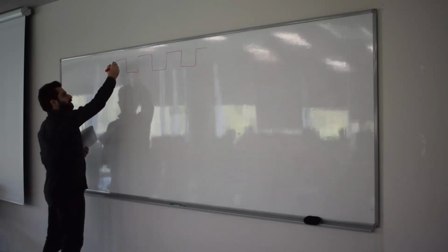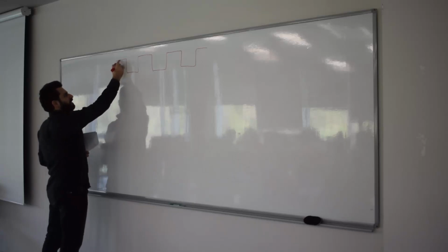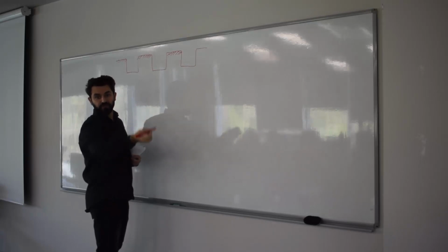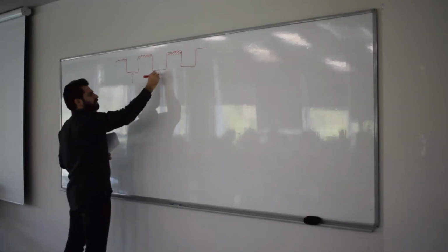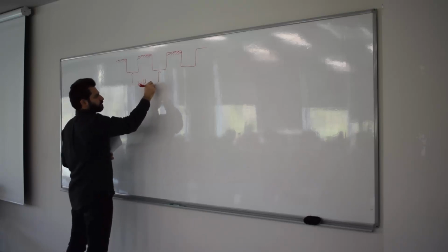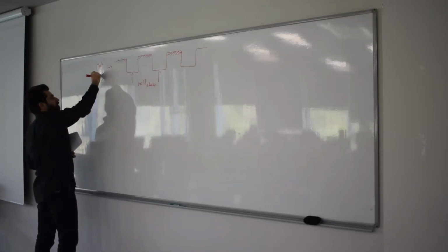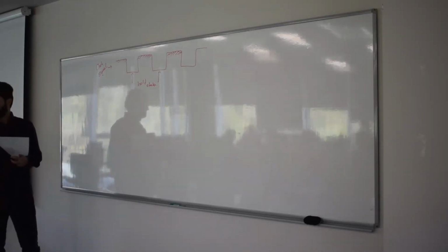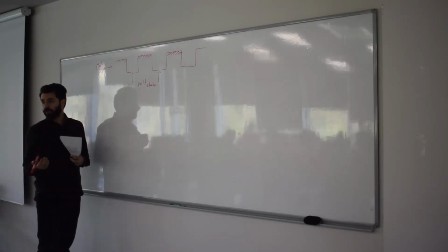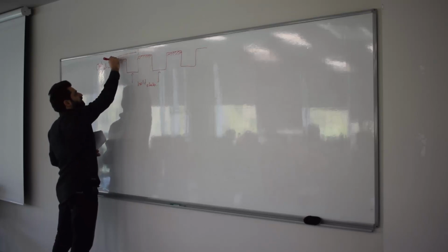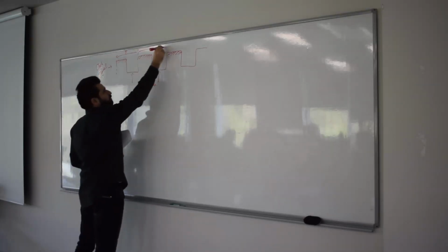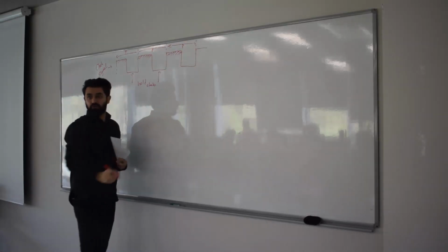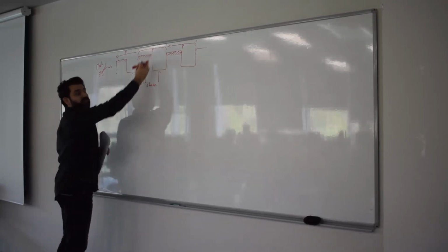So if you use a latch, these are the places where you're going to have a change, a copy operation of the input D. How about these? These are hold states. This is my clock signal. Now I'm transitioning to synchronous circuits where the clock is essential. Clock is a periodic square waveform, by the way. The period here is fixed. This is P, this is also P, and this is also P. It's a periodic square waveform, and the period can change, of course.